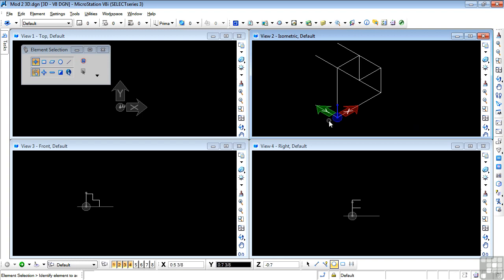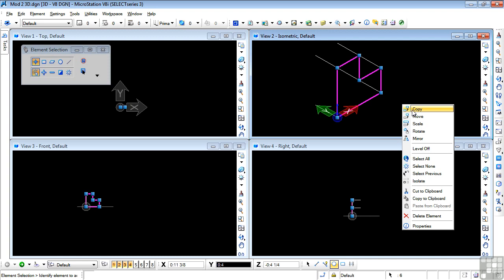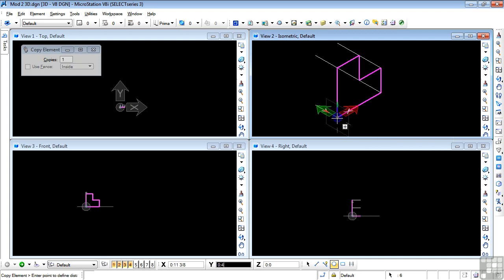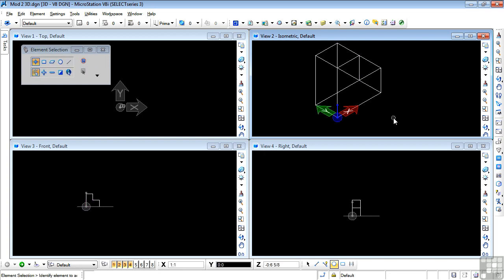So I'm going to copy the front face backwards. So I need that one, and that one, and that one, that one, that one, and that one. Do a copy from there to there. Now at this point it doesn't matter what orientation the compass is in, because snapping from point to point is an orientation in itself. So I can simply snap to that back end of the line. Left click and right click. And I have my step block views.